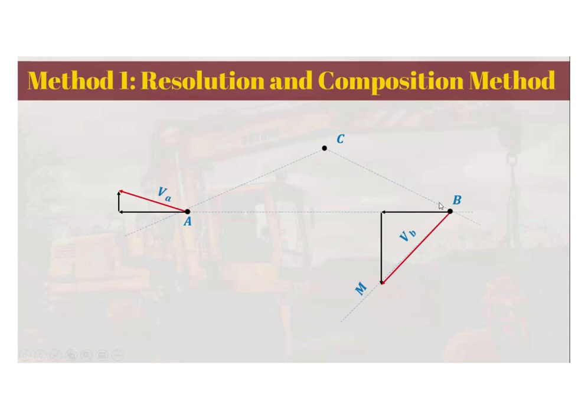We are going to resolve this velocity of B into components perpendicular and horizontal to this line joining B with C. So the perpendicular line is shown in the pink solid line. And the component along the line joining that velocity is, as you can see here, your BB and the vector CC1.